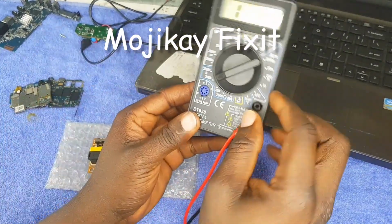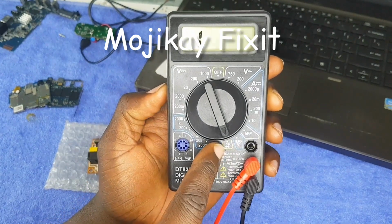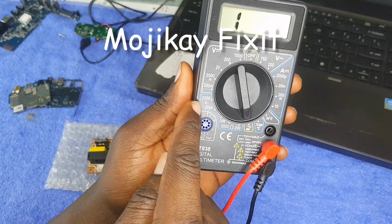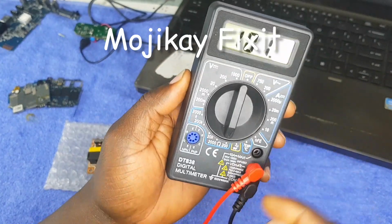Okay, so you put your multimeter, like I told you yesterday, this is diode mode and also buzzer mode. You can see the two is right there. So when you want to read the resistance, you see where these K's are. These are kilo ohms. This is the symbol of ohm right here. You move your multimeter here.